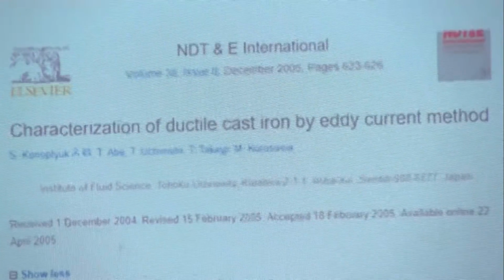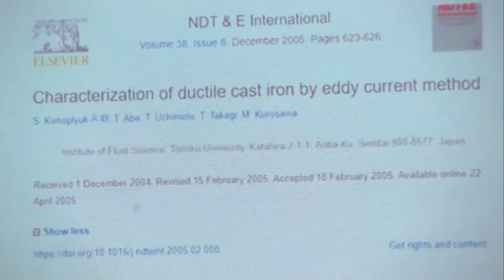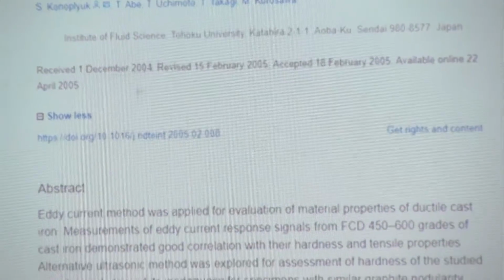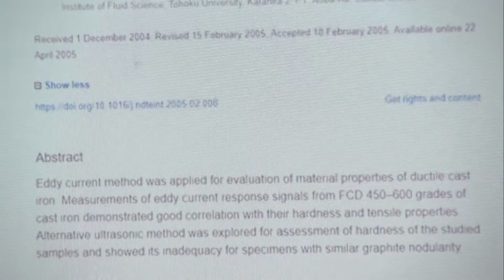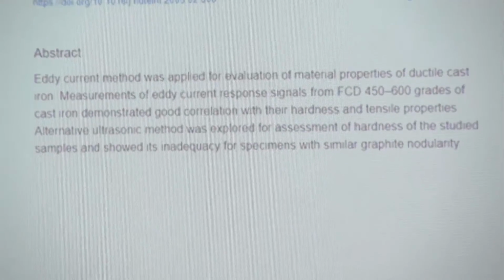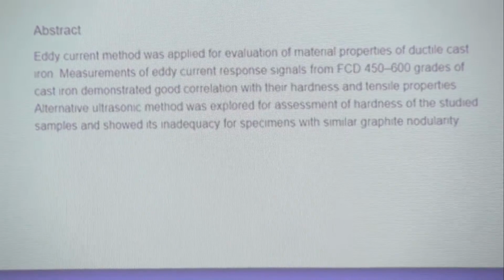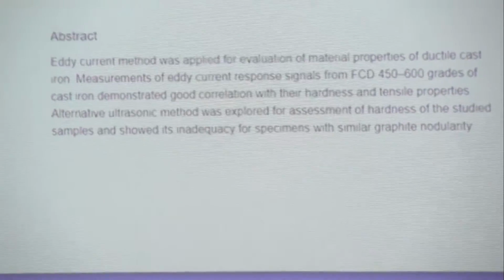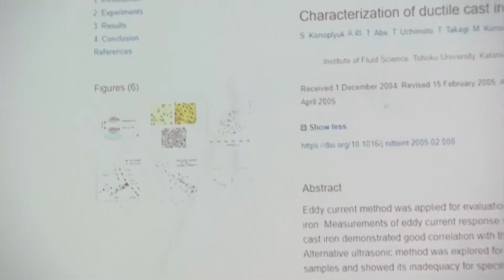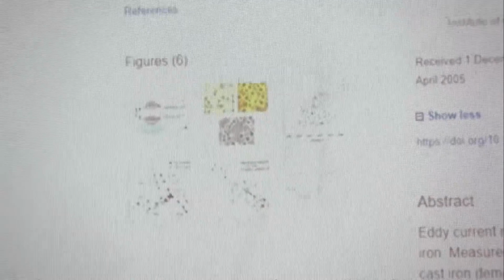Yes, that's correct. And in fact, this is used for non-destructive evaluation. Without even destroying the material, I can actually measure electrical properties under changing magnetic flux. Look at eddy currents. If the eddy current loops are very large, eddy current losses are very large, it tells me something. Typically, if the eddy current losses are very, very high, then that means the conductivity is very high. Eddy current loops are very large. So if there are cracks, the eddy current loops become smaller and the loss will change.